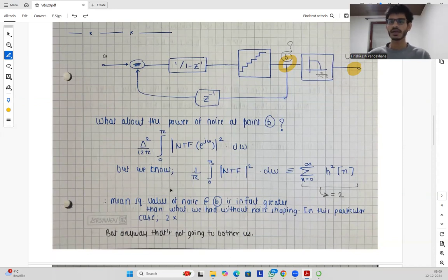Initially we had a noise, but while achieving noise shaping, the output of our delta sigma converter has a very complicated noise. But when we use a decimation filter, everything filters out very smoothly, and we have our input signal at very high resolution.